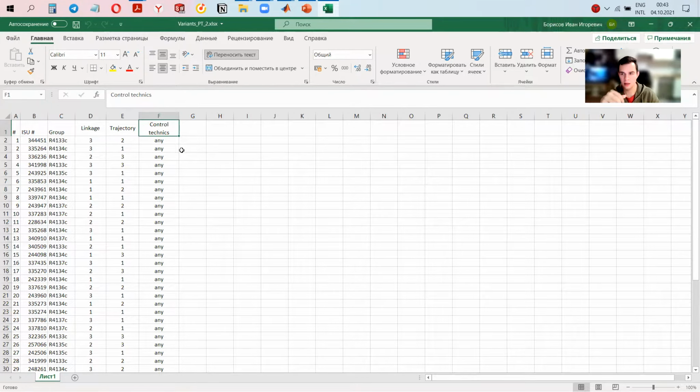In this video, I showed you PID control, but to do this PID control, you need to solve the inverse dynamics task. Position-based control, but for this one you need to consider inverse dynamics and the model. I guess this one is the most complex. The final one is the impedance control.